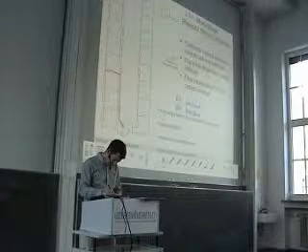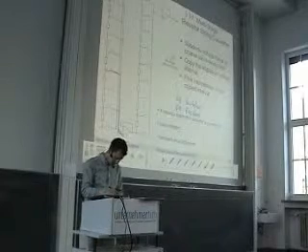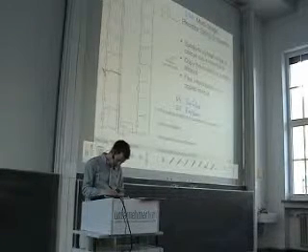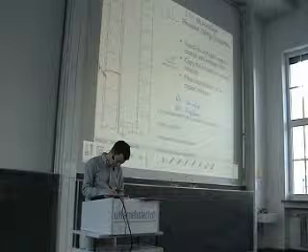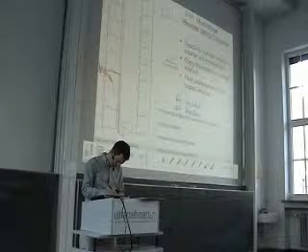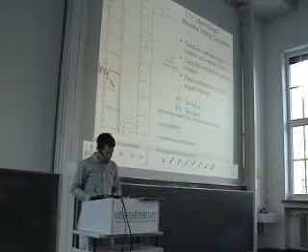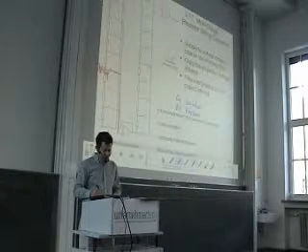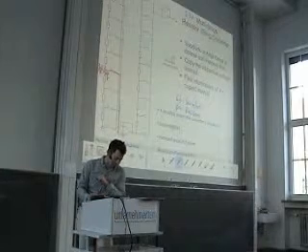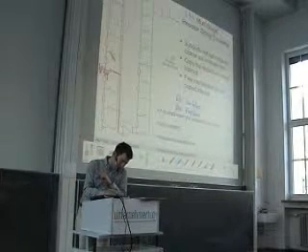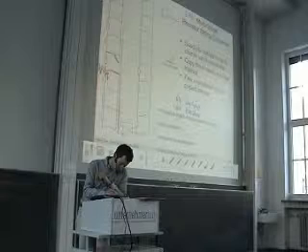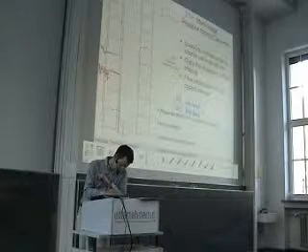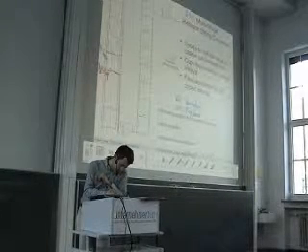and this switch connects here 3/8 times Vref to a first bus, and then we close a second switch, and the second switch is a neighbor of the first one. Let's say this one, we have here a 4/8 times Vref.